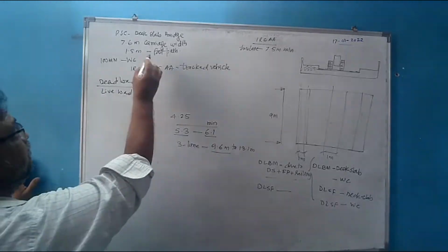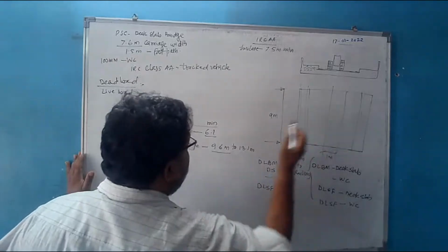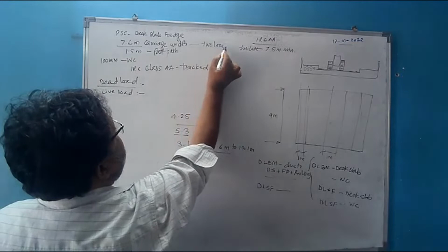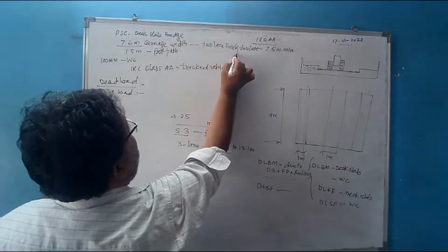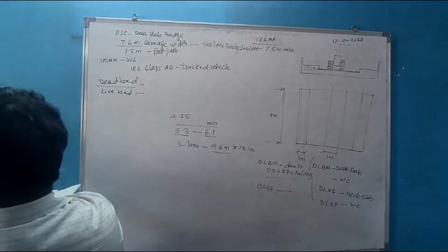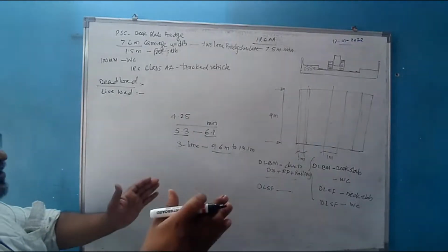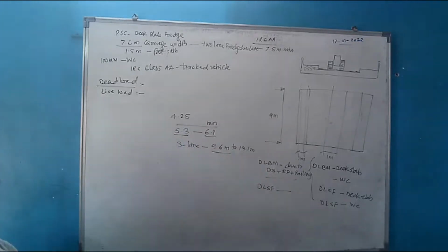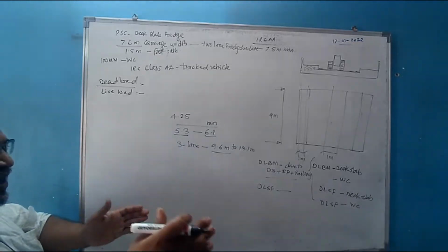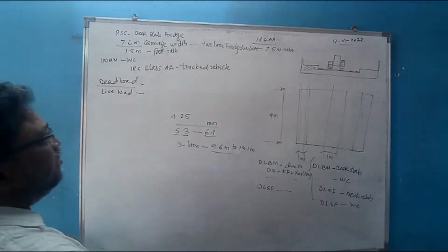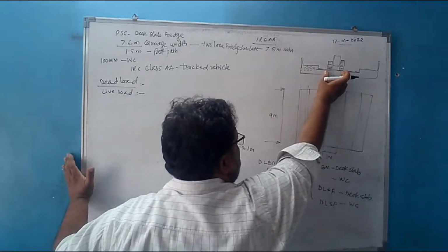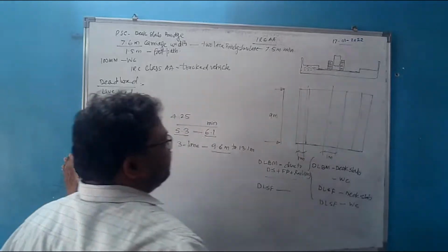It means that the given carriageway width is 7.6 meter. So it means that it is a 2-lane bridge. And what are the guidelines in the code? If it is a 2-lane bridge, for every 2 lanes of IRC class A train of vehicles, we consider only one IRC class AA vehicle will pass. So there will be just one IRC class AA vehicle on this carriageway width.